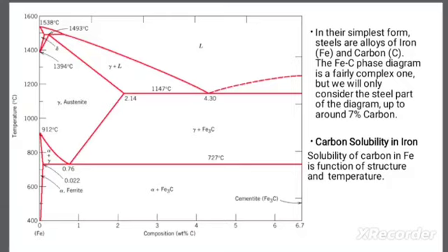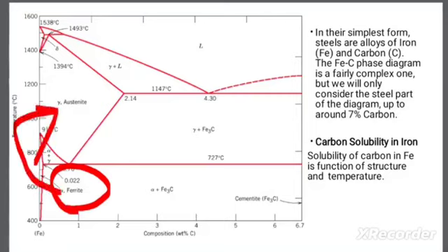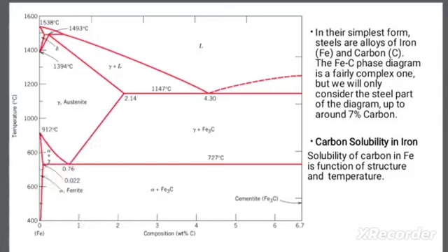At room temperature, the stable form called ferrite or alpha iron has a BCC structure, and when you are heating, ferrite changes to FCC austenite or gamma iron. Okay, so at the temperature here, nearly 600 degrees Celsius, when we are heating, this alpha region is transformed into the gamma region, which is FCC, that is face centered cubic.